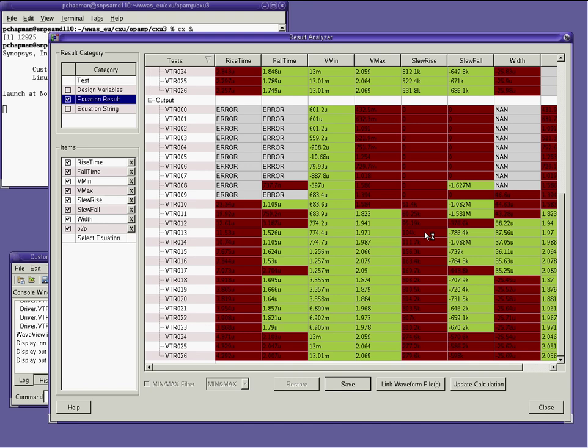Let's close that for the moment, because we can also see on the test list down here which have been submitted. Now what we're hoping is pretty soon we'll start getting some results, and indeed we've got things coming up saying success already. Now success in that context means the simulation actually ran and didn't give any errors, no fundamental failure in it. If we look at the table now, you can still see some of these NF figures, which means that particular simulation hasn't finished, so now we're starting to do analysis while the simulations are still going on in the background.